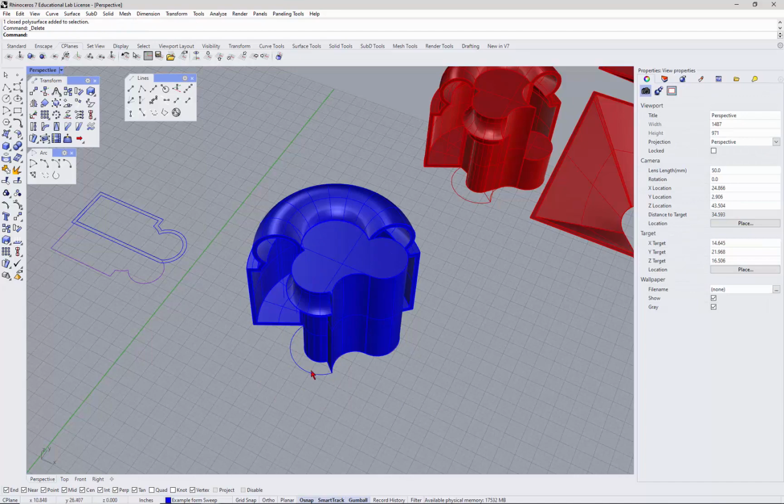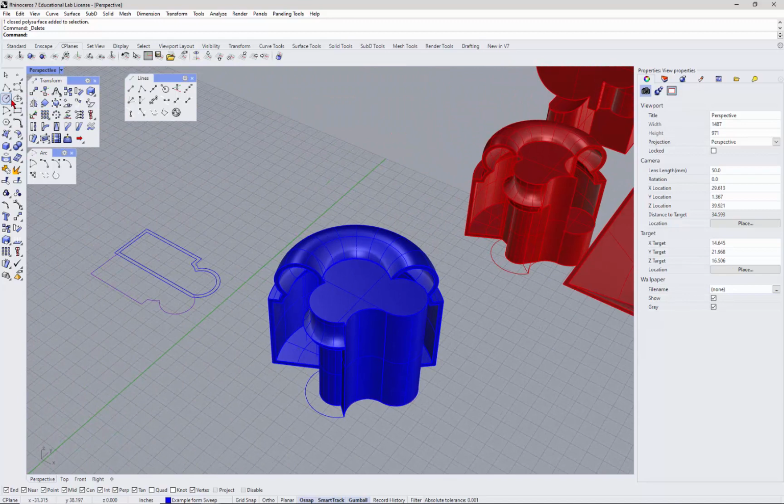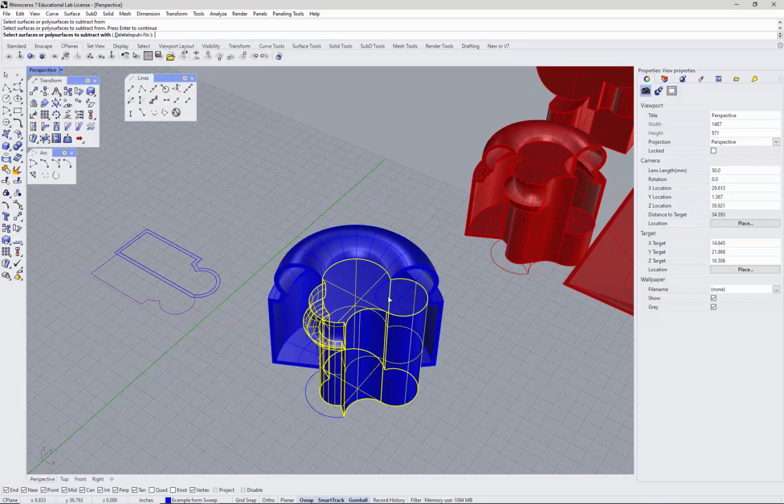Now I'm starting to get this cut out of there. Let's go ahead and open it up a little more, so I'll do a circle here, and let's extrude that curve from there maybe to the midpoint of there, and we'll cap this guy and we'll Boolean difference from this guy, that guy.